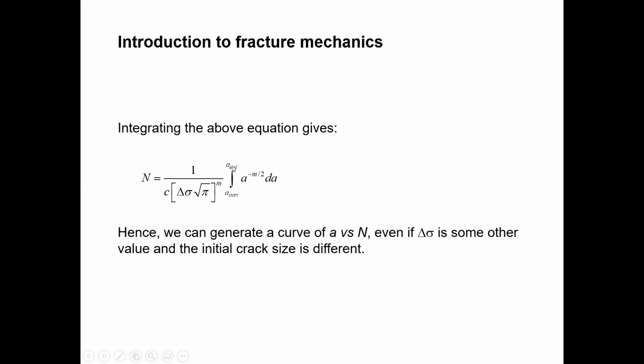That means sometimes the component width is a cross section, or diameter, something like that. So if you want to calculate the crack length until the middle of the cross section, you need to substitute in here, if it is a circular cross section, d by 2. That means half of the diameter, and you can calculate the number of cycles to grow the crack until that point. So I hope you understand how you can use that equation.